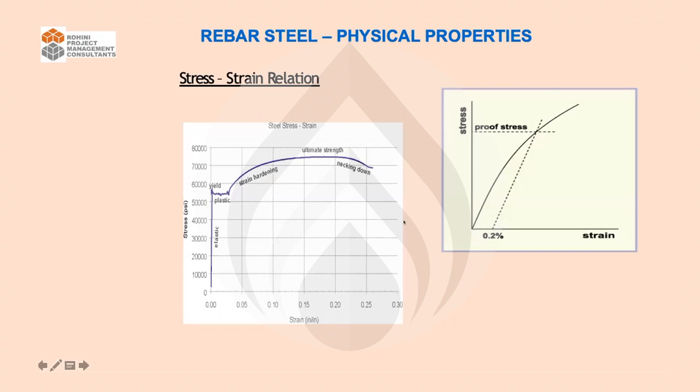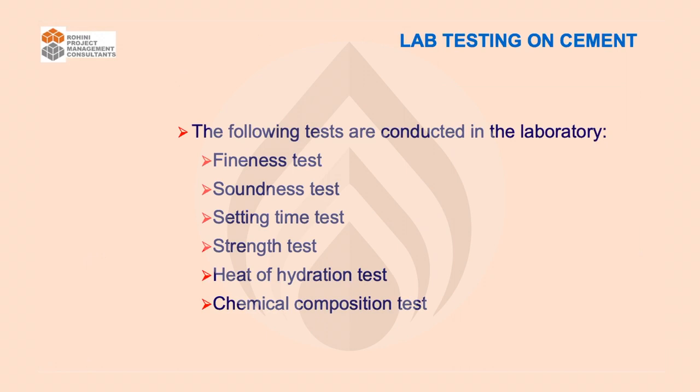Now, this is the very common thing in steel, right? You have a stress to strain relationship curve. This is how, at the start, there would be an elastic deformation when there is a bending and rebending, and then it gets into plastic, and then strain hardening, and then breaking down. There is a situation called ultimate strength, and when it gives off, that is the failure, which is recorded, right? So this is basically the steel portion of it.